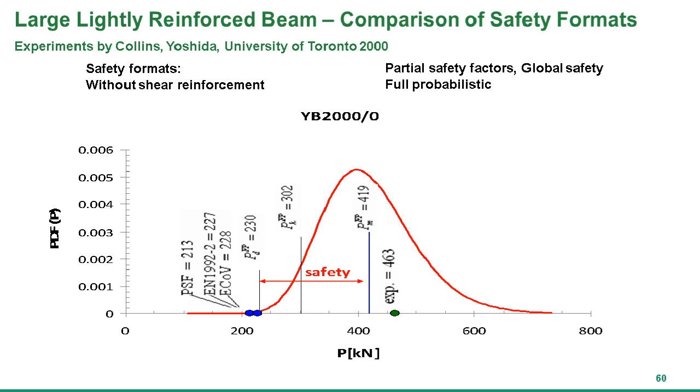This is a summary of this ECOV method for this example of a shear beam. And there you nicely see that the methods give very meaningful results. The PSF method, which is, let's say, most conservative, gives the lowest design strength, and the one which is most sophisticated, like the full probabilistic method, will give you slightly higher shear strength, basically, in this case. So in this particular example, things work very nicely.